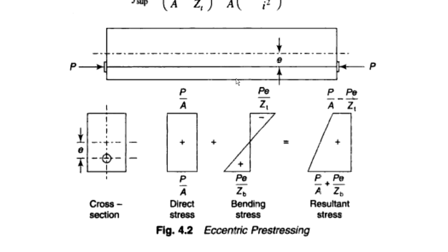At the top there is a tension zone, at the bottom there is a compression zone. Tension zone means the zone in which length increases, and compression zone means the zone in which length decreases. That means this beam is going to bend in this particular manner. That is why the topmost fibers are going to face the tension and the bottommost fibers are going to face the compression. So bottommost is positive, topmost is negative.